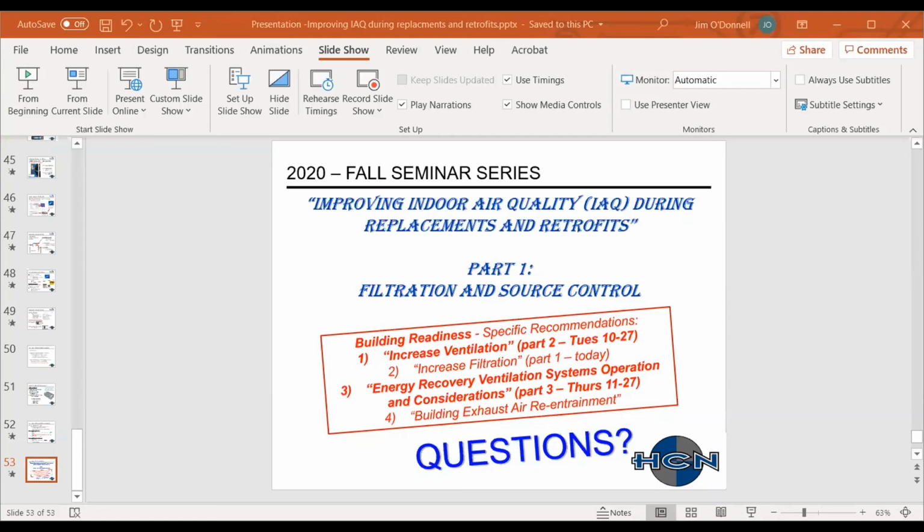I think the question is stating that the MERV rating with the GPS is due to an electronic charge on the filter. I don't find that to be correct. The GPS product is installed downstream of the filter. The ions travel in the unit and then the space, and they agglomerate the particles, and then the particles come back to standard filters.